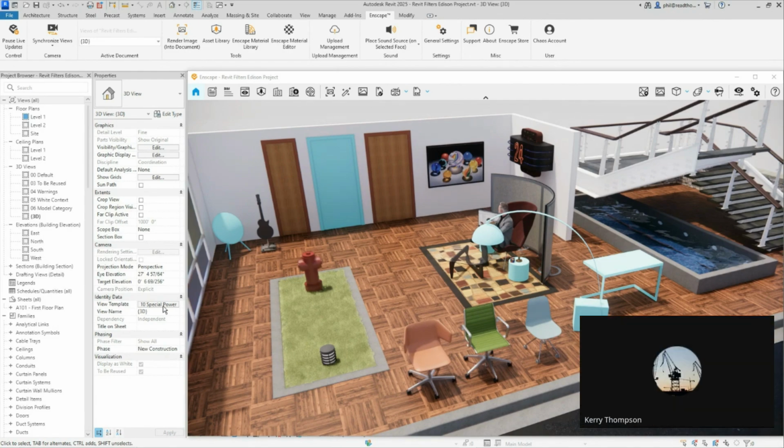I'll have a play. But the thing about it is I use a lot of Revit to aggregate other Revit files underneath and AutoCAD files and things. And it'd be great if we could get the linking working as well. So that the steel stuff's linked into my architectural stuff, and I want to look at the services plan overlaid on my framing, for example, without having to bring the model into one whole thing. So you actually link it through. So that was how I would start to look at it.